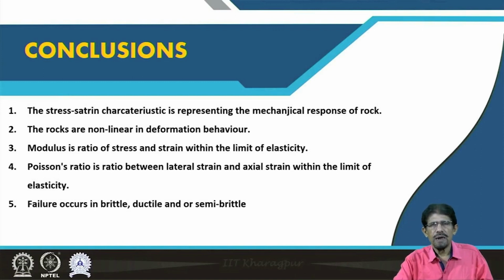Friends, if we conclude this brief discussion, then we can say that the stress-strain characteristic represents the mechanical response of rock. The rocks are non-linear in deformation behavior due to the anisotropic and heterogeneous nature of rock. The modulus is a ratio of stress and strain applied in all cases within the elastic limit.